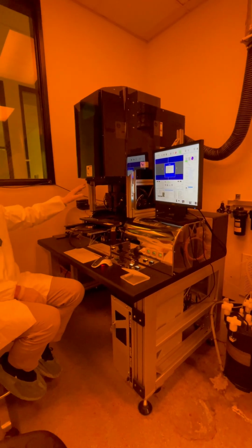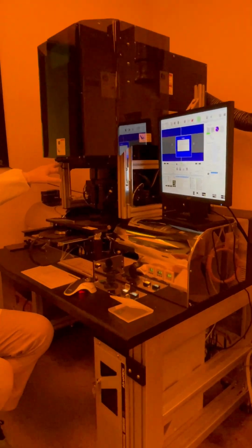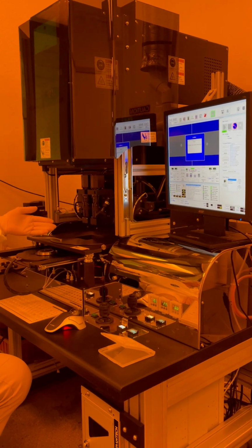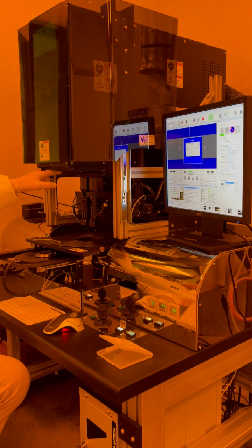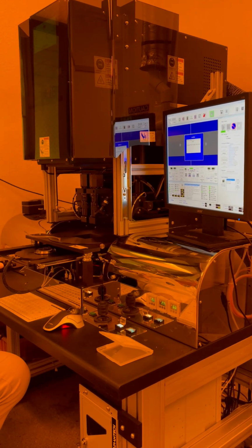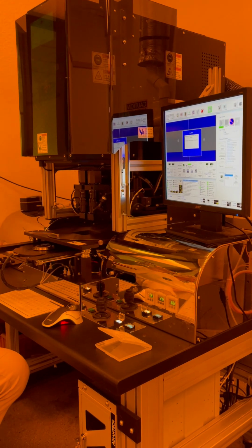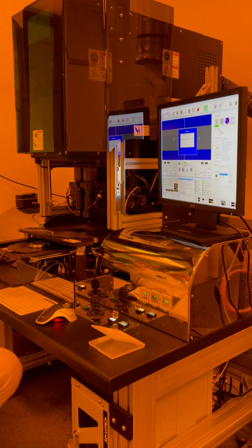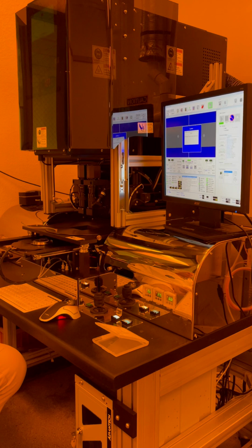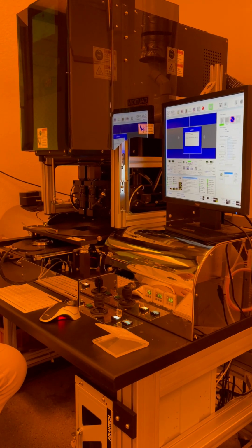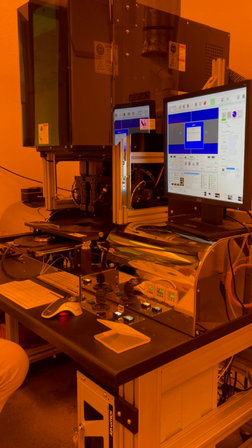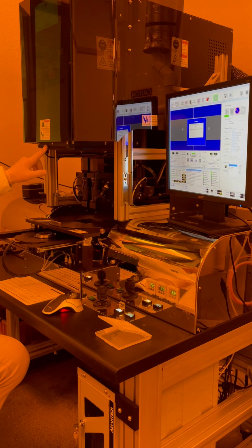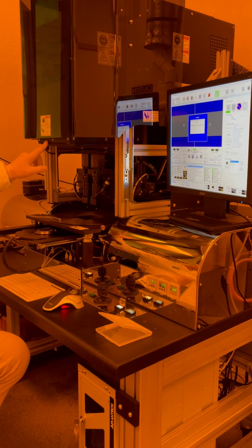And in some ways, it probably doesn't make much of a difference either way, but we like to think that it's a little bit better to keep things farther away, because when you have a lens surface, you're going to have some scattering onto that surface. And the farther away you are from that scattering, the narrower that angle is. For just the scattered light part, I'm not talking about the direct beam. So I don't know if that makes much of a difference, but we've printed with this exact light source design here. We've printed down to 0.4 micron. Okay. So it works really well.